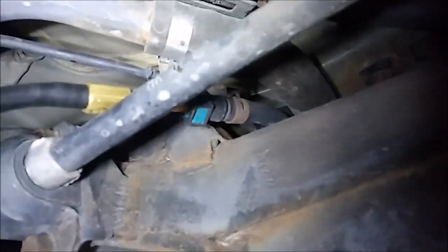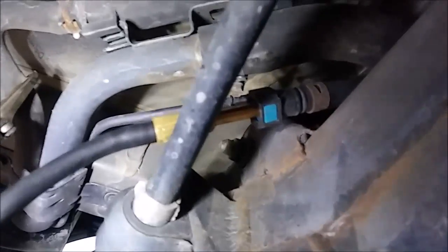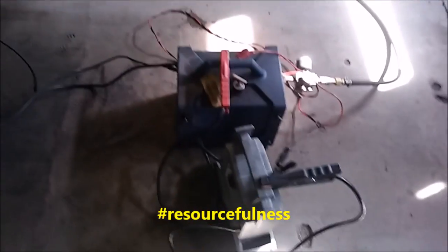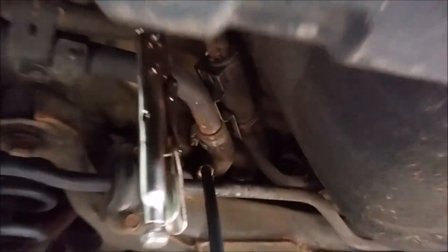Alright guys, so Hyundai's doing us pretty dirty on this one. The only test location I could find was this hose right here that hooks into that metal pipe you can see up there. All I did to tie into this is use an adapter from my fuel injection test kit. That's going down here to the floor where I have this smoke machine rigged up to my jump box. So this is how we're going to do this.